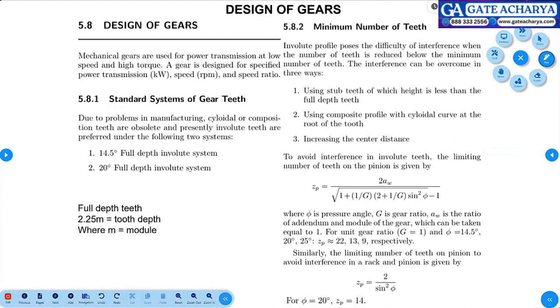So, design of gears. See, these gears are called positive drives. While belts and chains are concerned, if speed increases, what will happen to the relative velocity between the sprocket and the chain? There will be some dismantling, and it will slip off. With pulley and belt, when it reaches a critical value of velocity, the relative velocity will be lost, and the belt will totally come out of the pulley. So we call these slip drives.